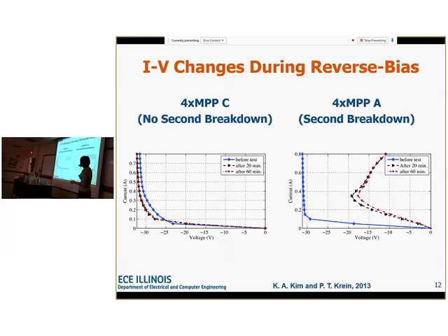This one, we're seeing this weird thing. I remember when I first saw this, I was really confused because I would see this with a few of them. We're ramping up the current, forcing the current up slowly in order to take these measurements. But the IV curve does not actually hook around like this. What's happening is, as we measure up to here, we're heating up the cell. It's changing its IV curve, and it's becoming like this. So it's kind of moving up and to the right.